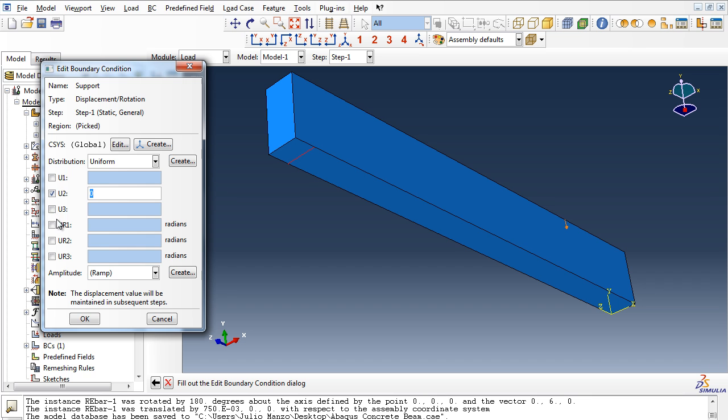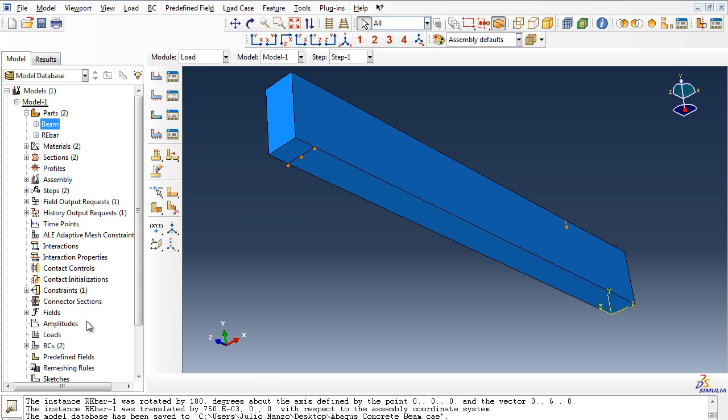We may need to go back and constrain them in case, when we're visualizing the displacement, it deflects as it's supposed to and then it also shifts, which would mean the support conditions weren't applied or defined properly. For now, let's just go with y, 0 movement in the y direction, and click OK. And you can see those symbols signify the constraint created on that boundary condition.